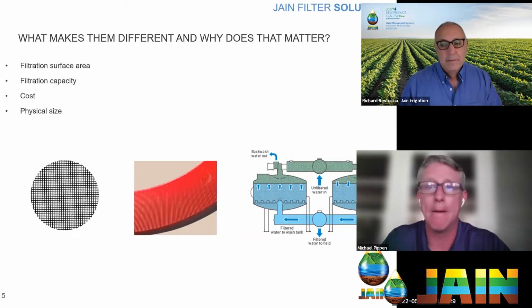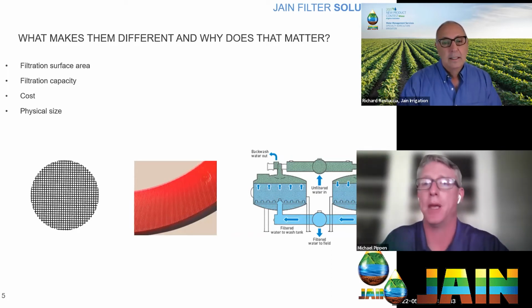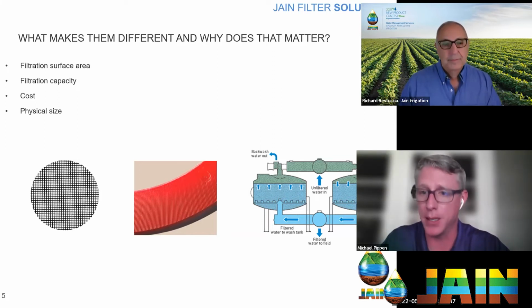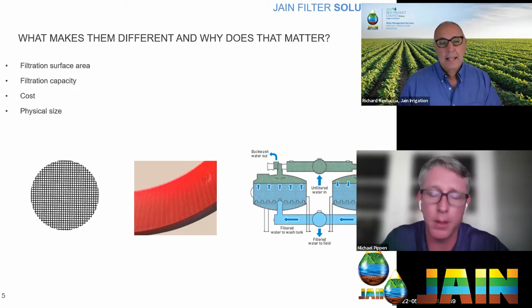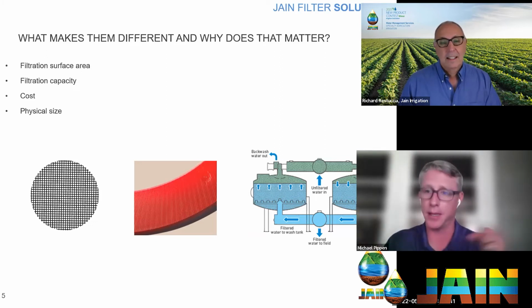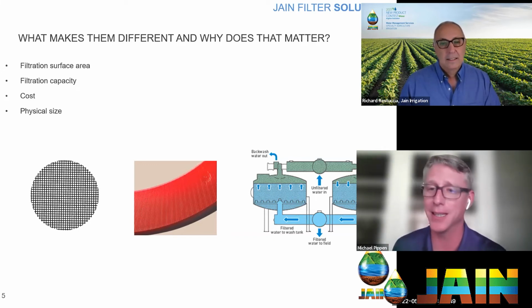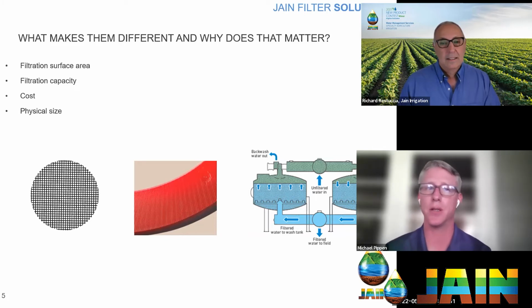That's a big piece of equipment. It takes a big piece of equipment to set it in place. It takes a good bit of labor sometimes to manage those things if you get them clogged up. There's a lot of things going on there, where a screen filter is pretty down and dirty in terms of efficiency. Basically no moving parts in it. And so there's always more considerations than just what capacity.